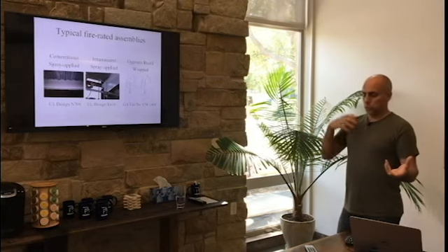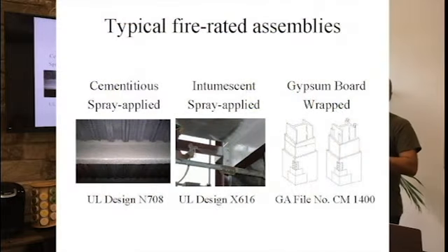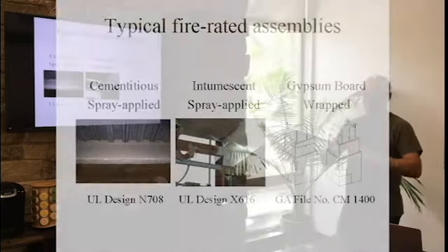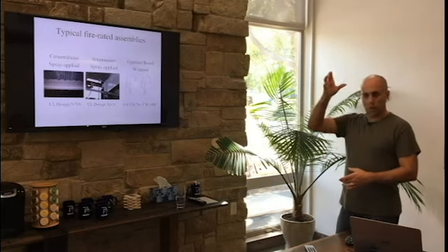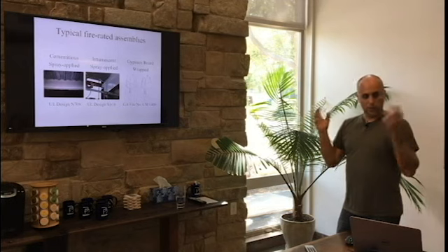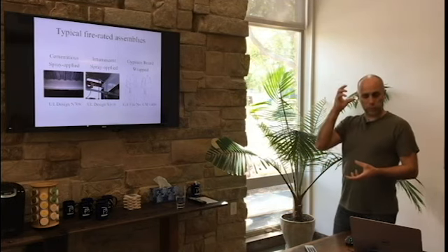If you have a beam that supports nothing but your roof, as long as it's encapsulated within that roof ceiling assembly, it doesn't need to be independently protected. That's one of those unusual conditions. Otherwise, columns are 100% protected inside the wall, if they're in a wall, top to the bottom of the column. I don't care if it's in the attic. It doesn't matter if it's more in the attic than it's not. The whole thing is protected all the way up.